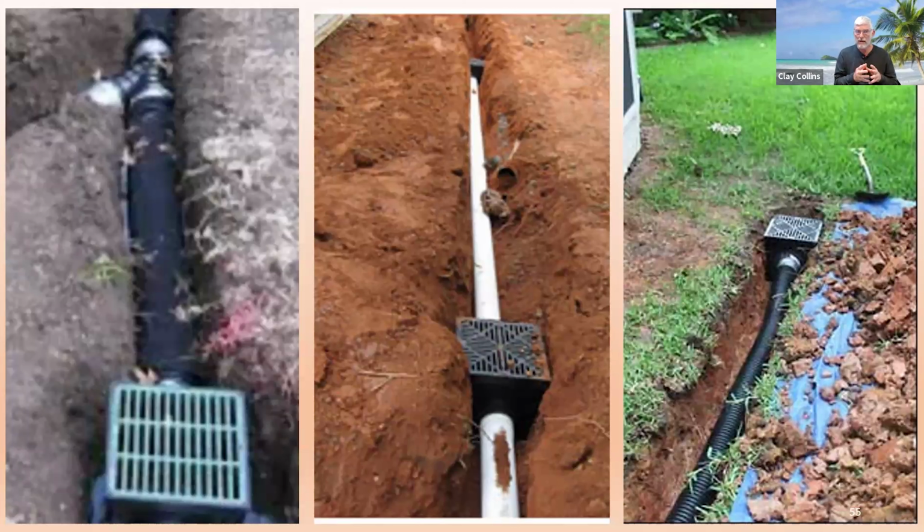Now you'll see on the left side, there is a wrap around the subsurface drain material. It's perforated. The foam wrap is what keeps, hopefully, or minimizes soils from going through there and clogging it up. And it's all sitting on a bed of gravel. Yes, that does mean that you leach out some of the water from that underground drain as it's moving towards its final destination, but that keeps it from overwhelming the discharge point.